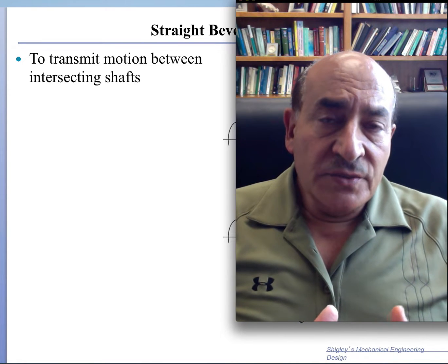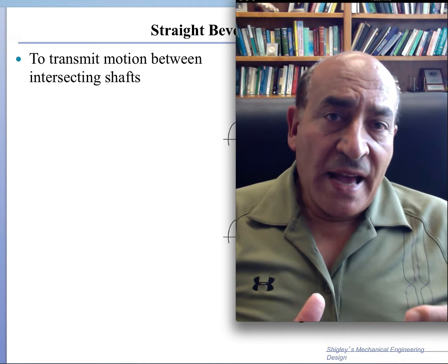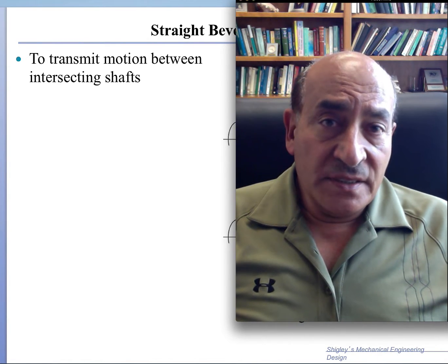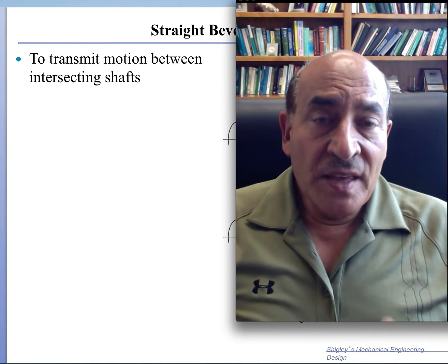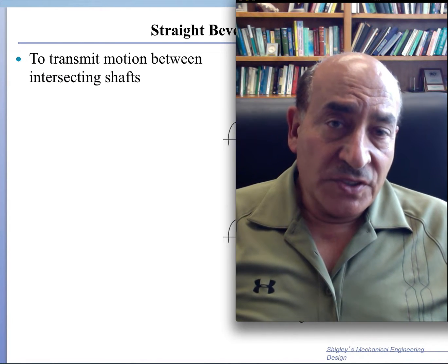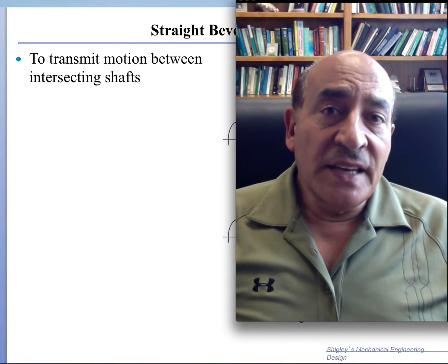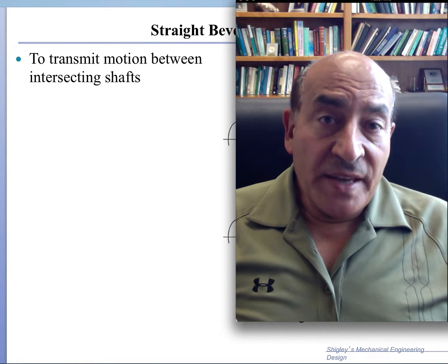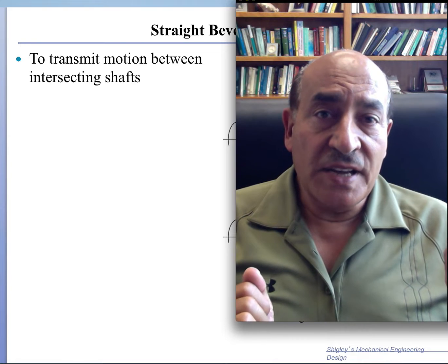If the shaft layout turns out to have all axes parallel to one another, we are in good shape, because we can use spur gears all the way through. Or we can also use helical gears, which transfer some force in the axial direction that we can take up with thrust bearings on the ends of the shaft.